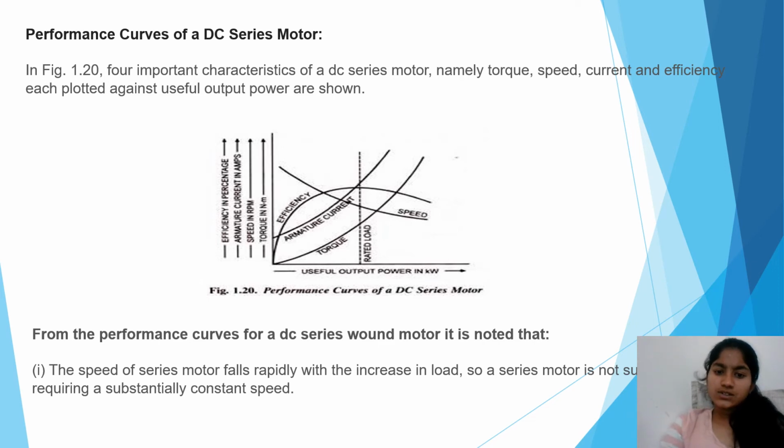What type of starting torque does a series motor have? In a series wound motor, the increased voltage causes both the armature and field current to increase. This allows the series motor to produce very high torque on startup for short durations. That is, operation of the motor at high torque, that is high current, for more than a few minutes can damage the coils.